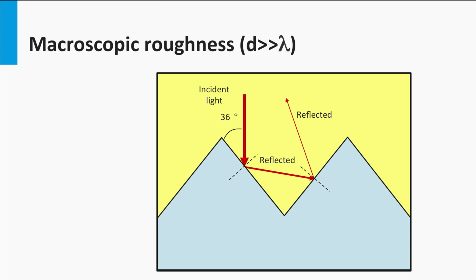Here the light can still be coupled into the silicon. Secondly, the scattering at textured surfaces will couple the light under angles into the wafer. This means that the absorption path length will be enhanced. This certainly enhances the absorption of light with a wavelength above 900 nanometers.